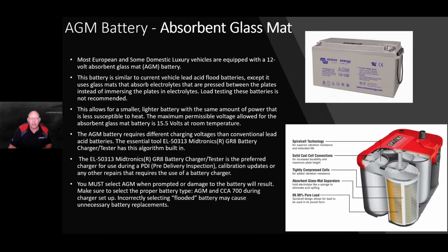The other thing you have to realize is that AGM batteries produce a higher voltage than SLI batteries. They produce generally right around 12.8 volts, sometimes up to 12.9, depending on how strong that battery is. So it's very common to see a car, like a BMW, with an AGM battery producing a little bit higher voltage that might seem like surface voltage.